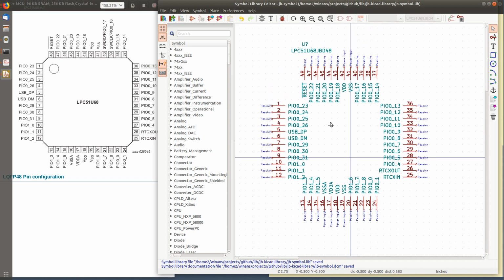This looks pretty good. Now, you'd be a fool not to double check your work here, because this will just propagate itself into your project or multiple projects as you move forward. You really need to make sure this is right. So one of the things I'll do right now is go through in my head and count 1, 2, 3, 4, 5, 6, 7, 8, and find out that there are exactly 48 pins. They're all numbered, they're all in order, and they go around like this.